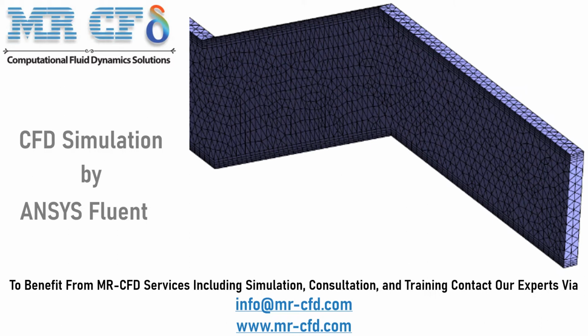The meshing of the model has been done using ANSYS meshing software, and the mesh type is unstructured. The element number is equal to 144,713, and a boundary layer mesh is used on the upper and lower walls of the channel.